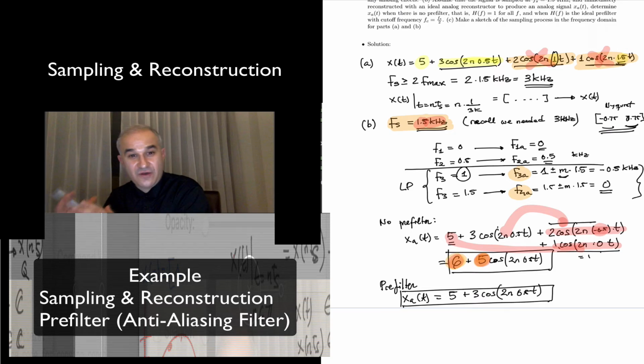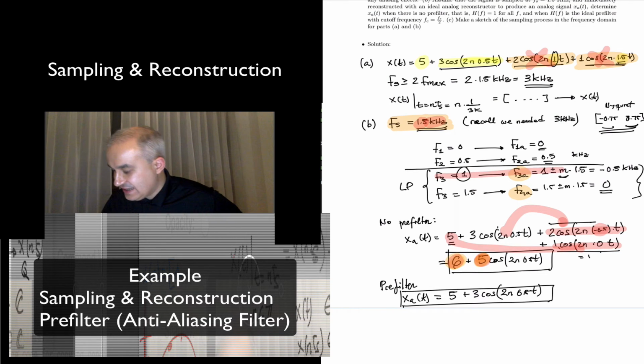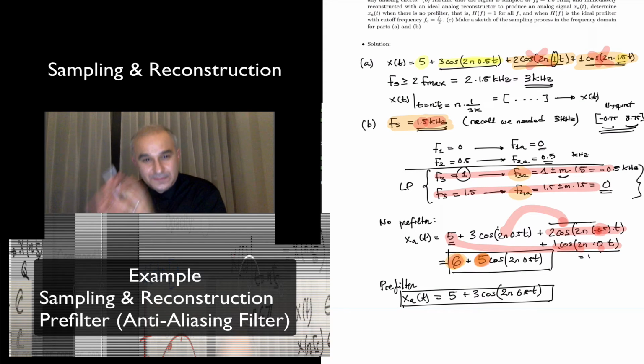And that's taken care of with the pre-filter or the anti-aliasing filter to eliminate these alias components, because otherwise, not only will you not get those higher components, you get something else, you will get aliasing, and those alias components will corrupt the spectrum that you could have gotten in the range that is appropriate. Okay?